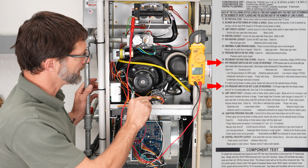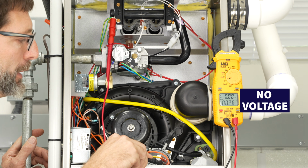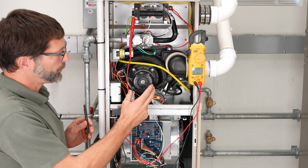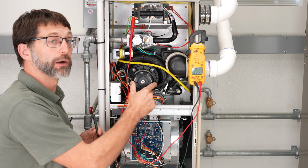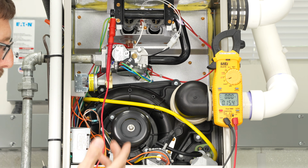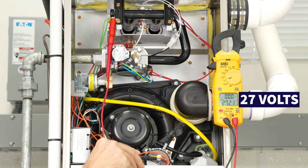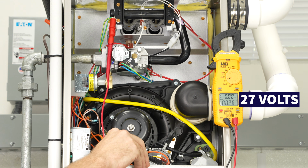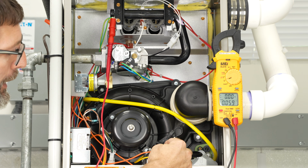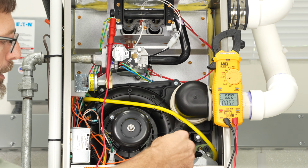And so we can measure right here. So we got 27 volts there, and we have no voltage right there, indicating that that electrical switch is open. So right now we know we have a problem with the inducer motor because it's not running. And if it was running, such as right now, and we still have the same problem, 27 volts there and then no voltage there, well, we know that we're not measuring the pressure on the pressure switch. It would be a negative pressure compared to atmospheric pressure.